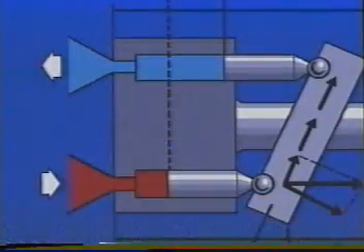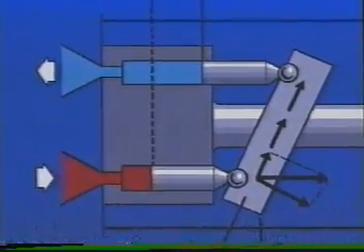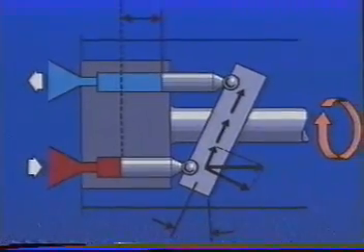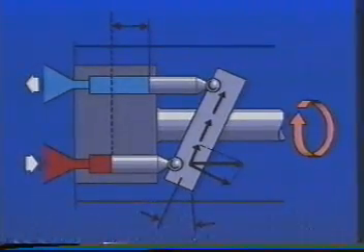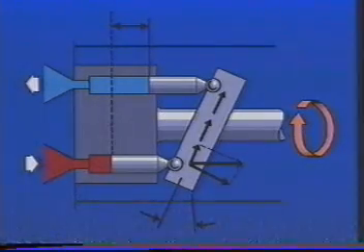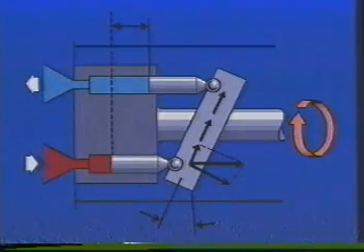A piston motor is almost identical in construction to a pump. The operation, however, is quite different. In a pump, the shaft drives the cylinder block, causing the pistons to move in and out of their bores, taking in and then discharging fluids. In a motor, fluid is pumped into the cylinder bores on the inlet side, forcing the pistons out against the swash plate, which, because of its angle, causes them to rotate, carrying the cylinder block and output shaft around with them.